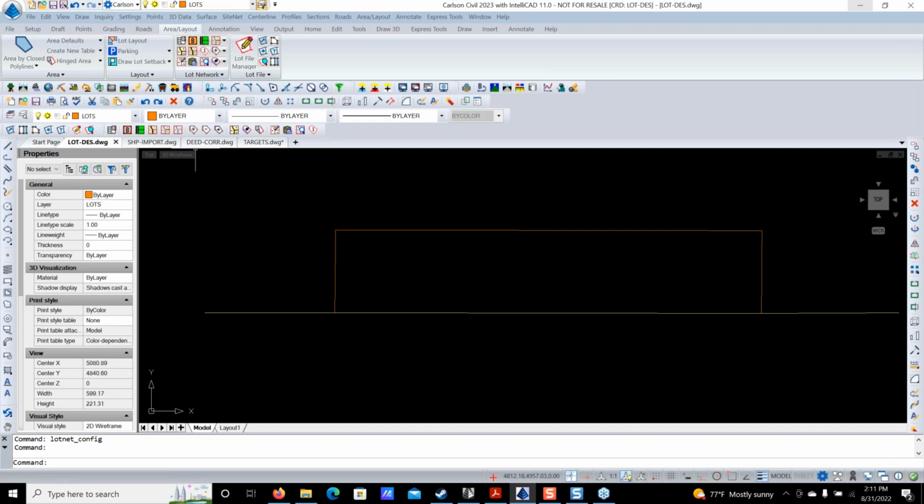So you have to set a boundary. I pick this button with the big B to set the boundary, and I pick this guy here, and I say that's my boundary. That's all. And then the next thing you've got to do, which is the one that I missed for a while because I didn't understand, you have to set the right of way. So I say set the right of way, which is the button right under it, and I just pick this guy here and press enter, and I've set the right of way.